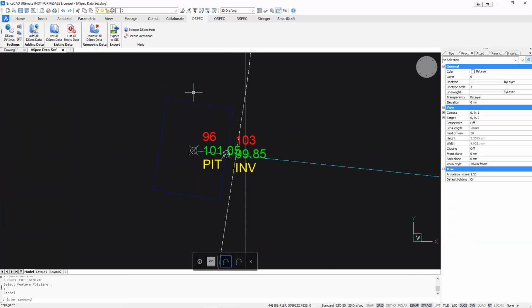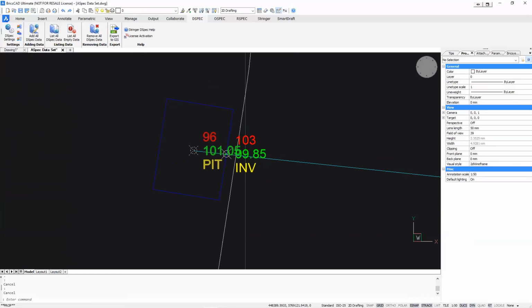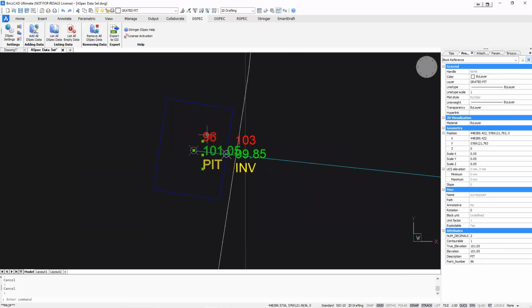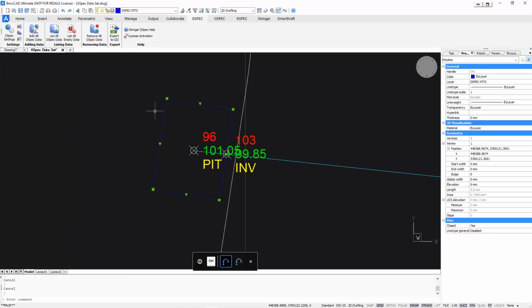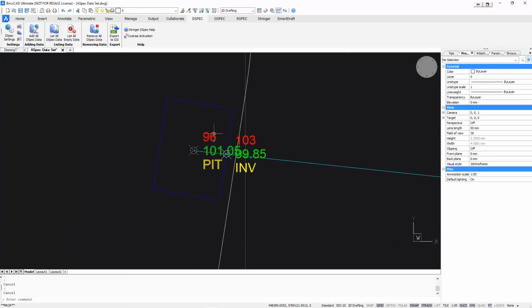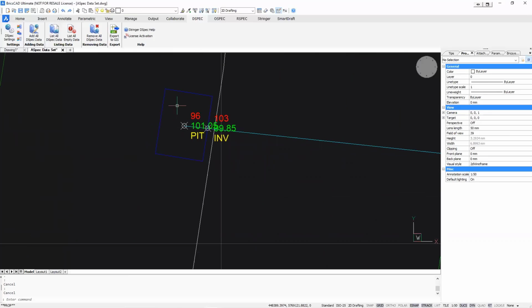Yep. So the polygon itself doesn't have any, well, now it has that information attached to it, but we've originally pulled that information off of this COGO point here. So the COGO point is vital in getting that elevation onto the polygon. That's why I had to select a coordinate point or a COGO point along with the polygon itself. Yeah, thank you. That's an integral part of using it, isn't it? We're not simply coming up with values assigned to the polyline. The point is the integral part of the selection process. Yeah, great. Yes, without that COGO point, you won't be able to fill in any of the rest of the information. It simply will not let you. Thank you.